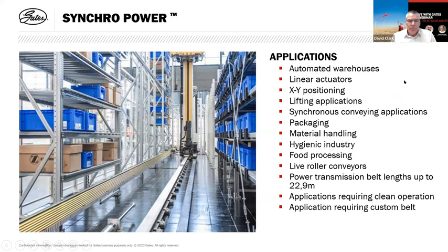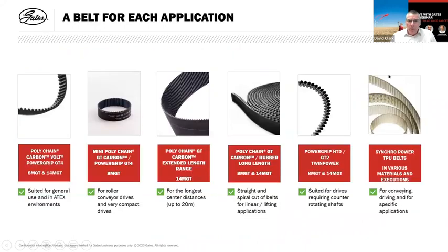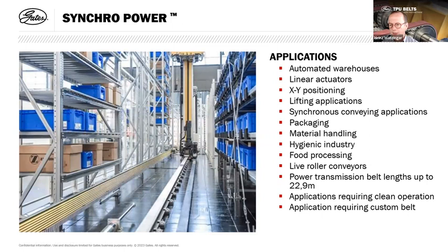It has all the advantages in that high capacity, reduced maintenance. It's a very resistant belt. The thermoset polyurethane is resistant to most acids, chemicals, and water. Of course, I will caveat this by saying dilute acids. We've run this drive submerged in oil. We've run it submerged in water, and it has extremely good resistance to both and very good lifetime when running in very contaminated environments.